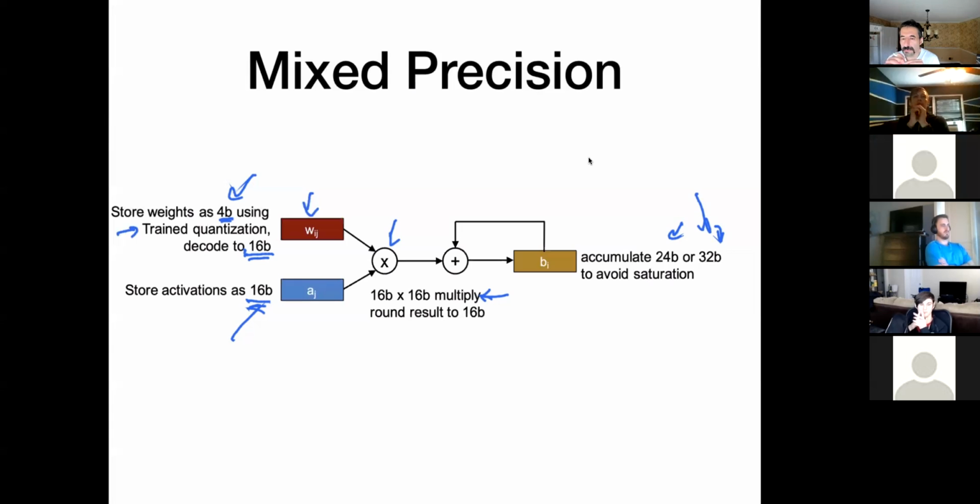My intuition would be that the weights are something that you have a whole lot more of than the activations. And because we have a lot more of them, we want to use a lower precision for those. Because that would give us, I guess, less DRAM access, or we would be accessing memory far less with those.